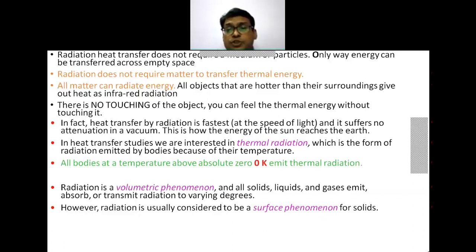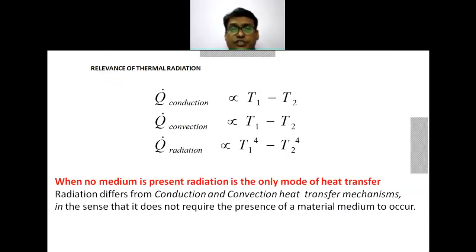Now it is very important: all bodies at a temperature above absolute zero emit thermal radiation. Radiation is a volumetric phenomenon, and all solids, liquids and gases emit, absorb or transmit radiation to varying degrees. However, it is considered to be a surface phenomenon for solids.